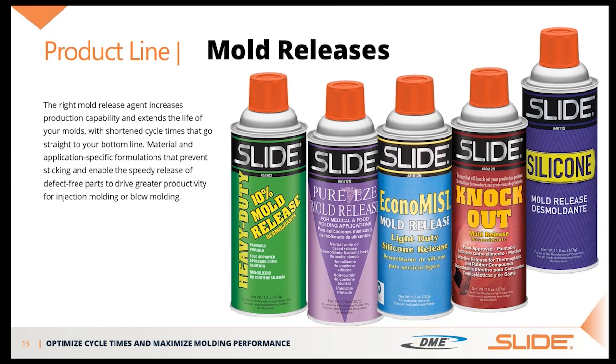These are both glycol based. So they're not silicone, they're glycol based. If you are having trouble with something sticking, but you can't use silicone, if you need it to be paintable or whatever, the Knockout is the way to go. The difference between the Knockout and the heavy duty 10% is Knockout is 5% glycol, and the heavy duty 10% is 10%.